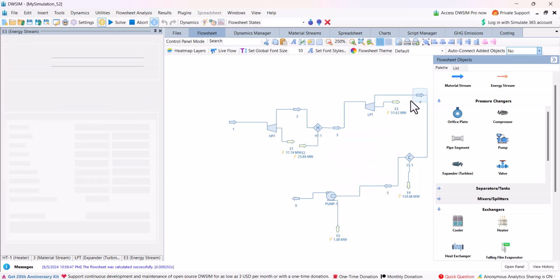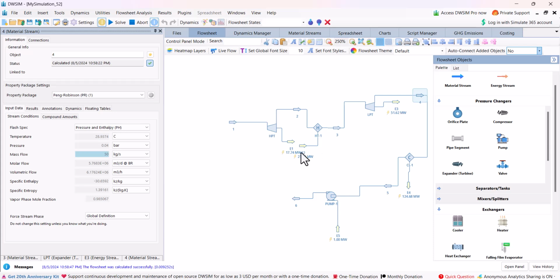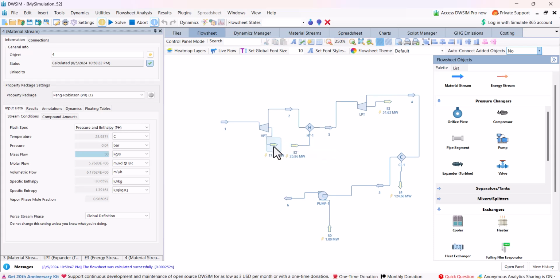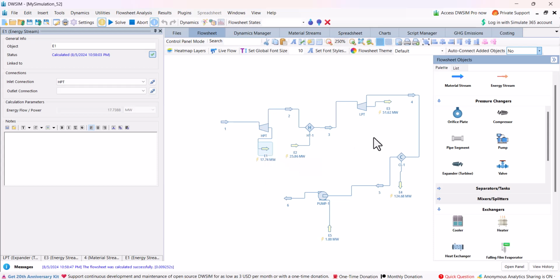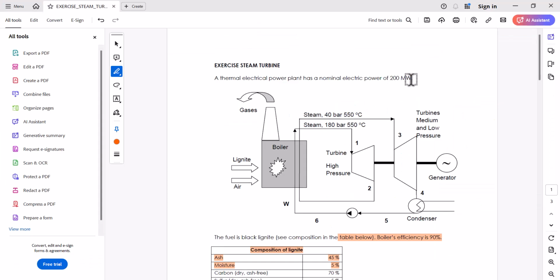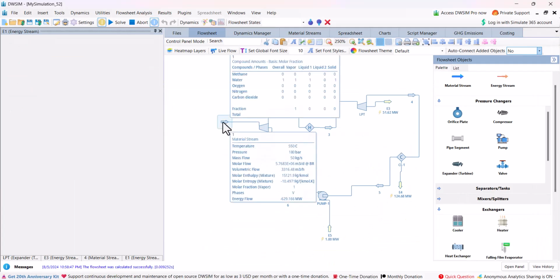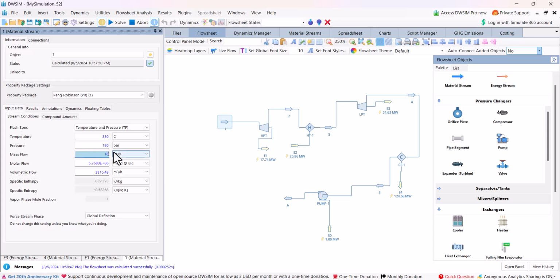Yes, and then you see we are getting 17 megawatt of electricity from the high pressure steam turbine, around 18 megawatt, and 52 megawatt around from the low pressure steam turbine. In total it is 51, 17, 68 and 70 megawatt, but the problem states we have a 200 megawatt power plant. So either you can just do hit and trial, add water flow rate 200 and see how much it is, or you can use... now it's 53 and 154, around 200, so you can play with that.